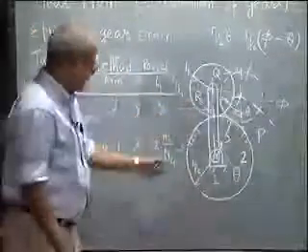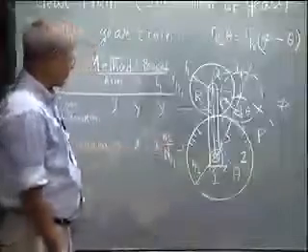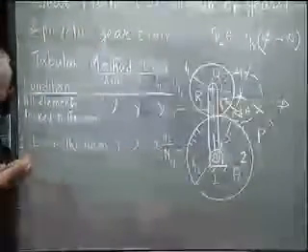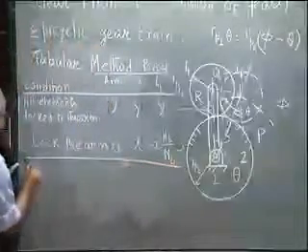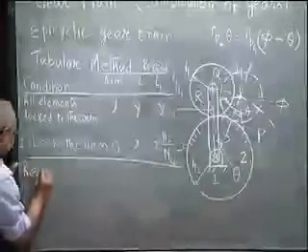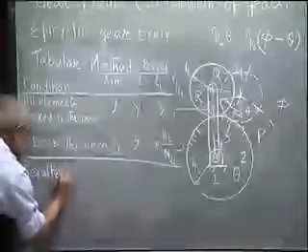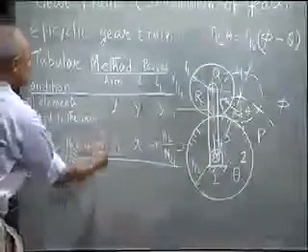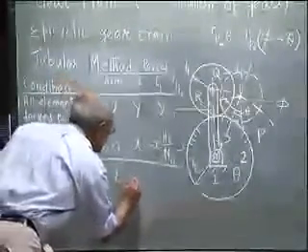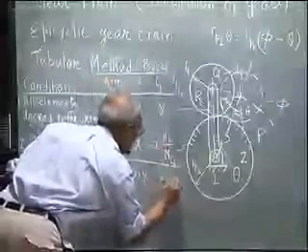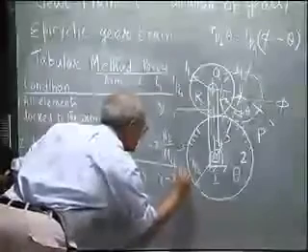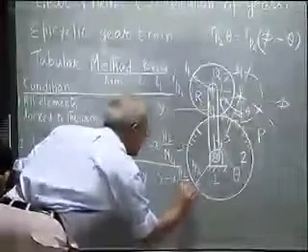Minus because it is external gearing and the inverse ratio of the number of teeth. Then add these two, and that is what you get as the resultant motion. So here it is y, here it is x plus y, here it is y minus x into N2 by N4.